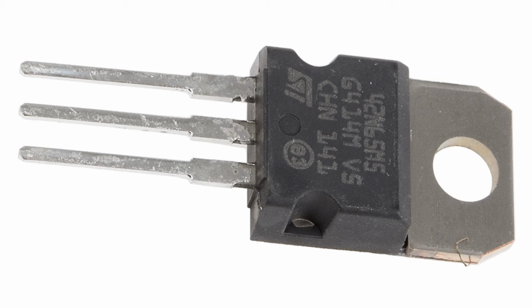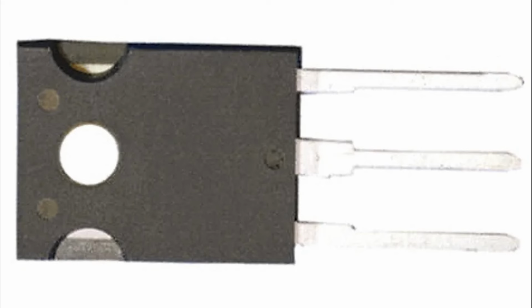Here's a detailed overview of these properties. 1. High input impedance. Description: power MOSFETs have a very high input impedance due to the insulated gate oxide layer, which requires minimal current to control the gate voltage. Implication: this property allows for low power consumption in the gate drive circuit and enables easy interfacing with digital control signals.